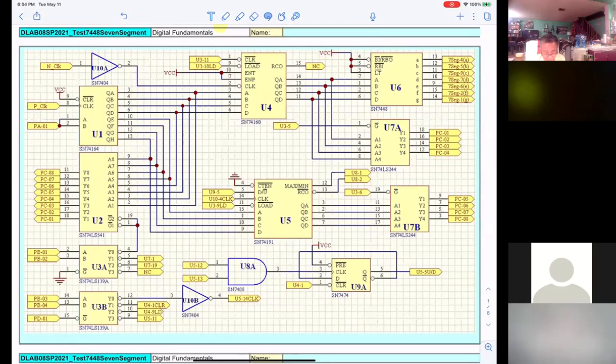You're talking about loading, right? Right. Loading, because for load and clear on U4, pin 1 and pin 9 go back to U3, 10 and 11. And I didn't hear you talk about enabling anything, when you were talking about those two.